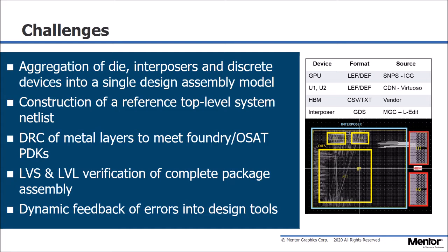The first is bringing all the elements together into a single accurate design model that can be used to drive downstream design and verification. As part of this is the need to construct a top-level or system netlist so that connectivity can be managed and verified during design and final verification. Once implementation of the various levels of substrate has been completed, then the task of verification can begin.